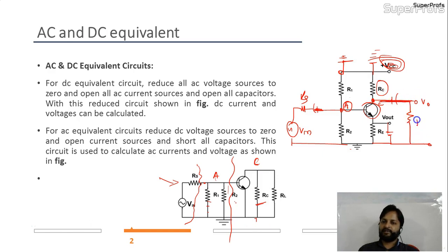And in the original one, you have load resistance RL connected from C to ground. So this is the C terminal, RL connected C to ground. What about this capacitor? This capacitor is shorted. So if this is shorted, RE will be useless. So this is your circuit. This is your analysis, AC analysis.